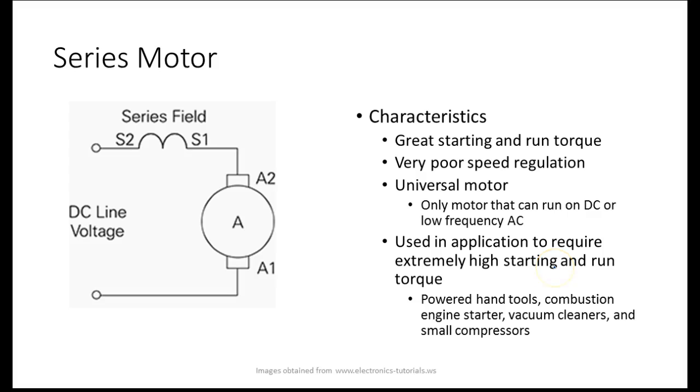Series motor. These guys are neat. Great starting and run torque, very poor speed regulation. Also called a universal motor. These guys here will run on AC or DC. Of course, you have to be real careful with the frequency, so that's why they call it universal motor.